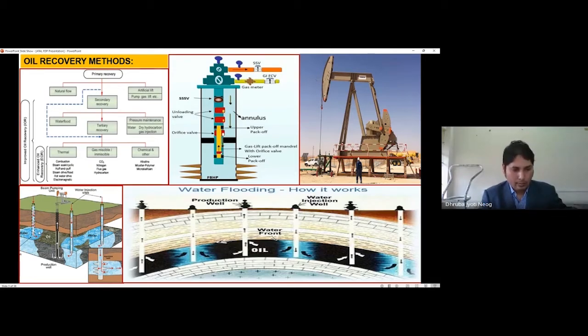This is required whenever it is anticipated that the inherent energy of the reservoir is not adequate and is not helping in the displacement of oil towards the producing well. So we require maintaining the reservoir pressure, because reservoir pressure is the driving force for the crude oil to flow from the subsurface reservoir through the well and through the downstream flow line into the surface facilities.